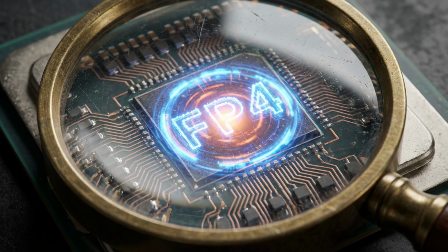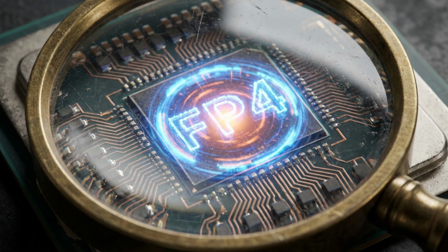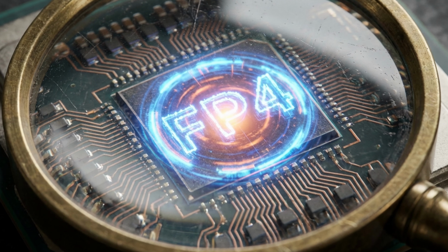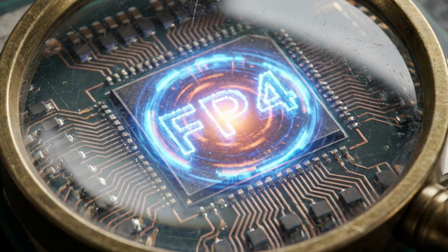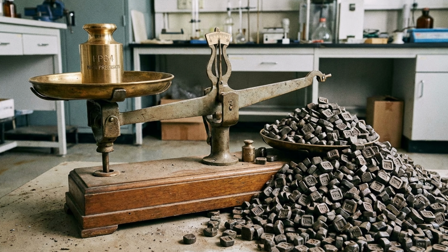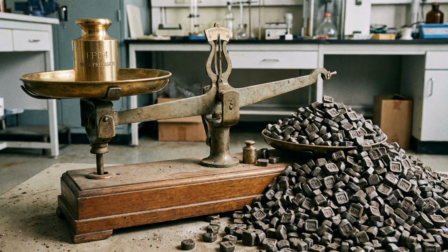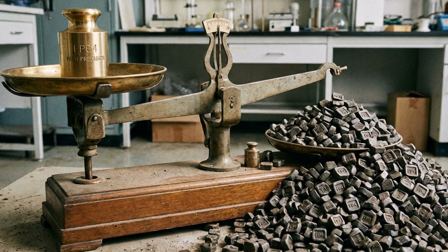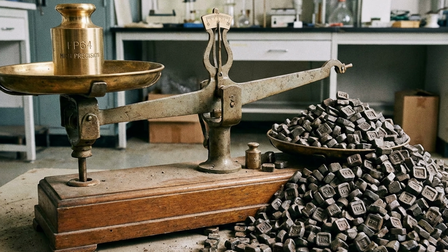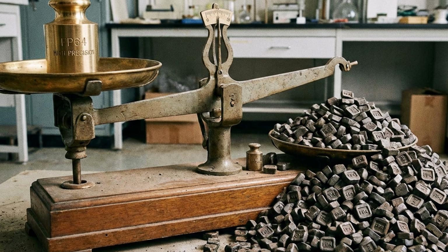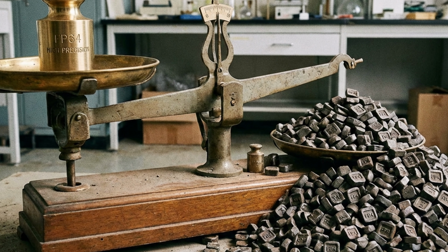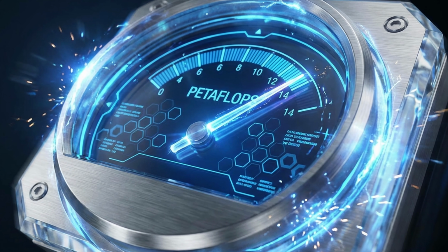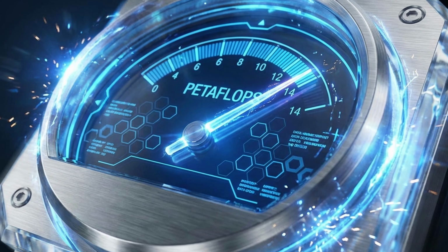At the microscopic architectural level, Blackwell introduces the 5th-generation tensor core, specifically engineered to support an even smaller mathematical format known as 4-bit floating-point precision. To squeeze maximum possible throughput out of modern language models, engineers intentionally sacrificed traditional high-precision supercomputing math, dropping 64-bit performance drastically to heavily over-index on these ultra-low precision formats. The 4-bit tensor cores provide an astonishing 14 petaflops of raw compute power on a single chip.